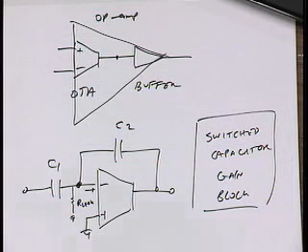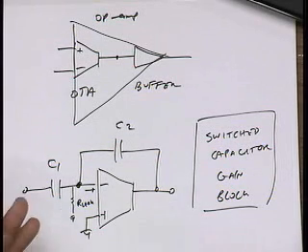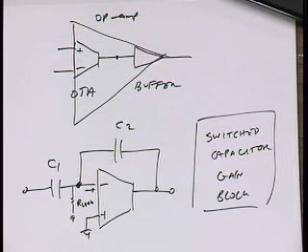Well, let's think, why would it be an advantage to work in discrete time? For instance, you could just turn off all the circuits, turn them on, capture the signal, and then turn off again. That would be one advantage, right? So every clock edge, your circuit could turn on, do something with the signal, and then turn off again. Well, you definitely could do that if the clock is slow enough, right? If you're in an application where the circuit turns on and settles fast, much faster than the clock rate, then discrete time can be lower power.